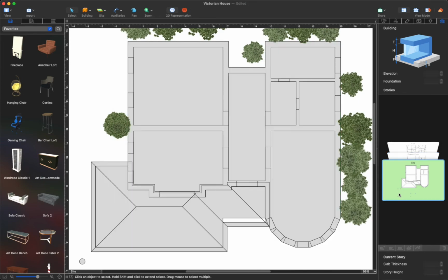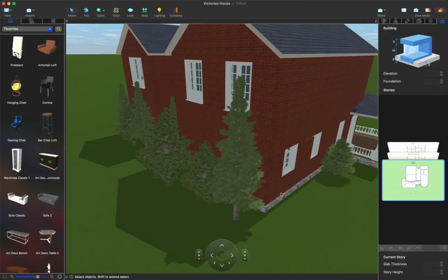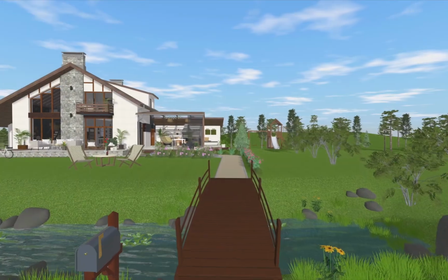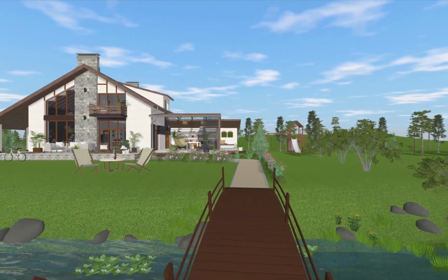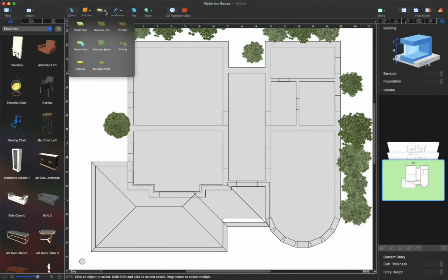The site layer accompanies the ground floor layer. They both have the same elevation level and both must be present in any project, but they have different purposes. The ground floor is intended to keep the parts of the building located on the ground level. This can be the ground floor itself, terrace, and so on. The site is used for standalone structures, such as a garden pavilion, pool, fence, or for outdoor plants. The site layer is also used to model the terrain.